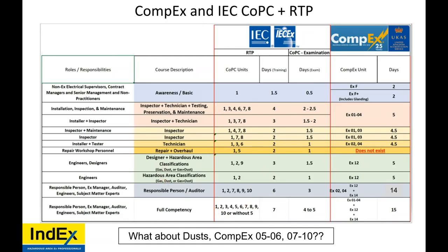And also a very important point, like non-electrical explosion protection. It's also not considered in many cases how to do non-electrical installation, machinery I'm talking about, in possible hazardous environment. That's something currently not really well addressed in any of the competency measurement tools.